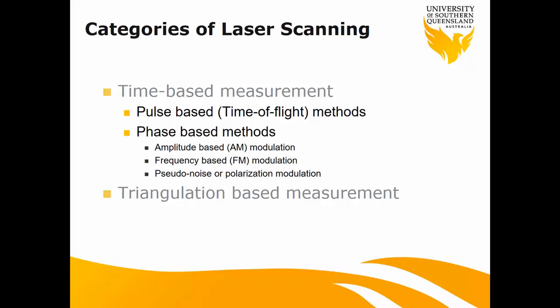So the second way, we directly measure the phase shift. The laser beam travels from the instrument with an initial frequency phase. When the laser beam returns to the instrument, there will be a change in the phase angle or frequency, which we call the frequency shift.